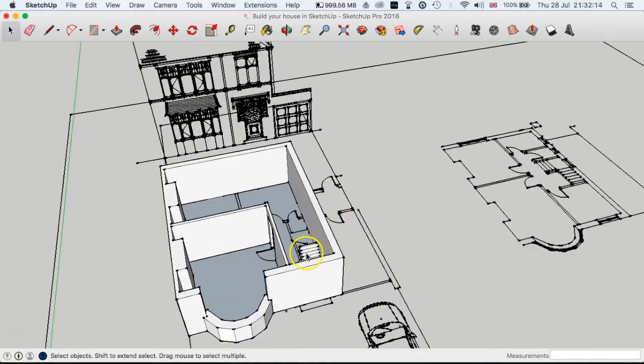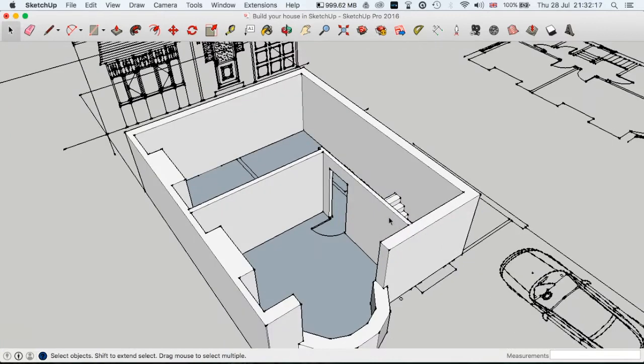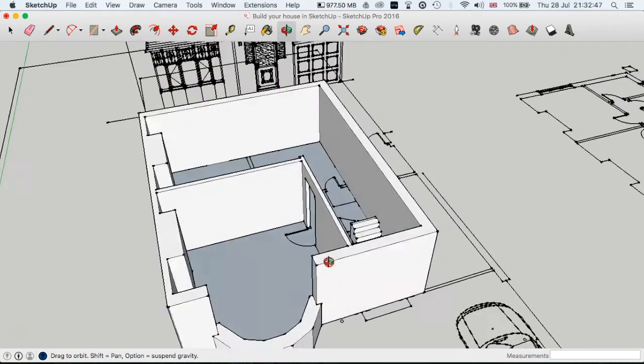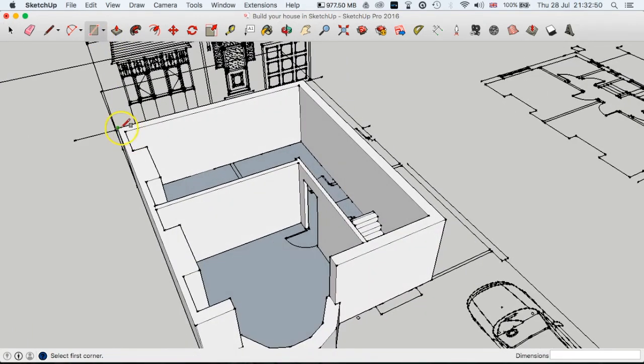Now what we do, once we've done that, is we need to figure out what the depth of the floor is. Now often around stairs it's quite easy to do this because we can figure out what the ceiling to the first floor level is. There are other ways to do this as well, using external measurements, etc. So for instance, you can take a measurement on the internal, on the first floor up to the sill of a window, and then do it exactly the same on the outside to a certain level that you know, and then you can work out what the thickness of the floor is. So the easiest way is what I'm going to show you on this.